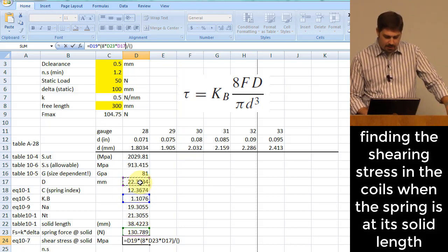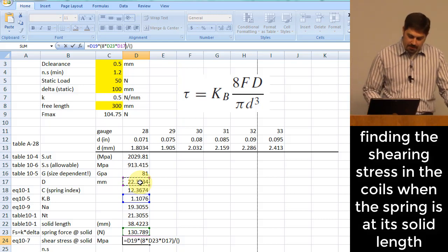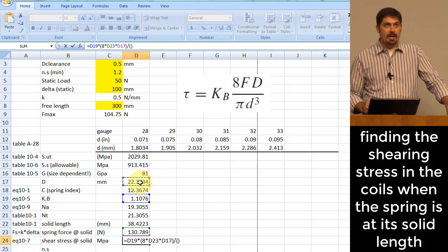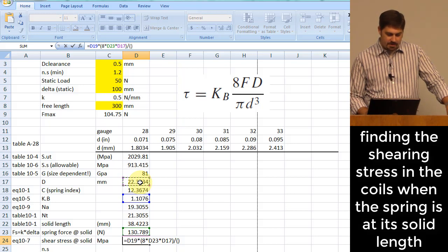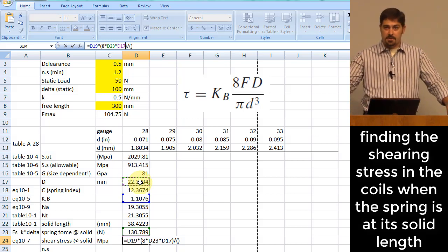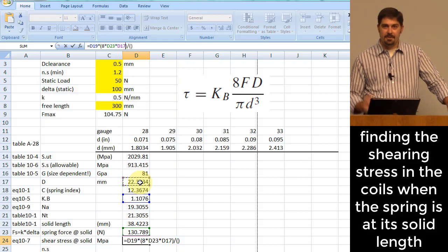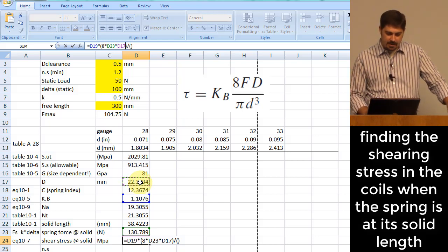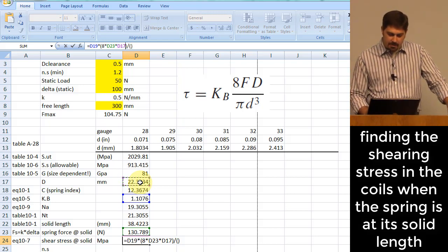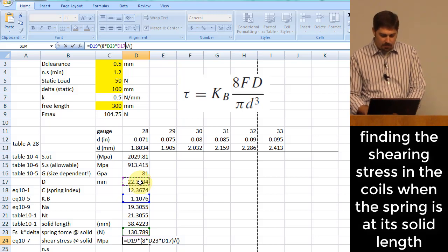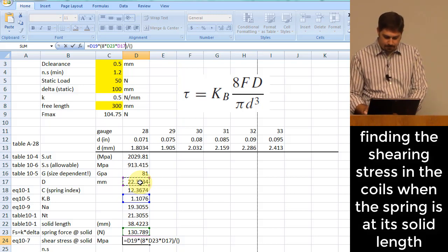Quick question. How do you think I might want to handle this in terms of units? You do have some choices, but one way to handle it is with base units. I think that's what I'll do here. So whatever comes out of this will probably be in pascals, unless I do some other kind of multiplication. So I'm going to handle it with base units, which means I'll take my diameter here and divide by 1,000.